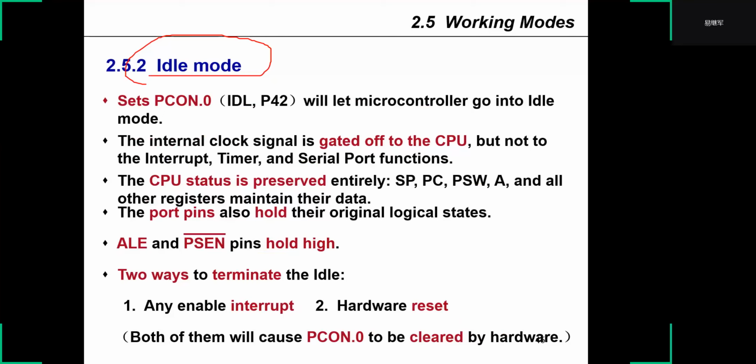The special function registers maintain their data. The port pins also hold their original logical status. ALE and PSEN pins hold high. This is what happens when we set the idle mode.